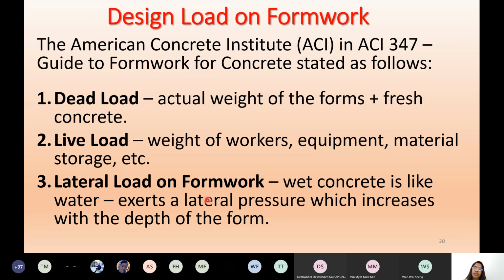So you need to include it. You cannot calculate it exactly, but you can take a percentage of this loading for lateral load on formwork, which is due to shear load from the water in the concrete mixture. As the head of water and the slurry grows, the pressure onto the formwork also increases. So care should be taken to include this type of loading as well.